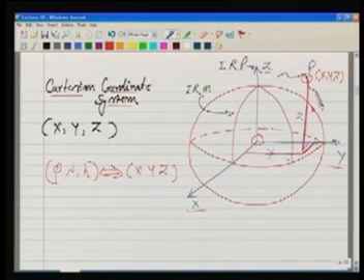So basically the very first measurement that the GPS will give us will be in the WGS84 coordinate system, that is, with reference to this geocentric coordinate system, either as x, y, z or as phi, lambda, and h. It gives me the coordinates of any point on the surface of the earth. So henceforth, whenever we are talking about the position given by GPS, we mean either of these two, and we can transform one from the other. So in any format we can write the coordinates given by the GPS.